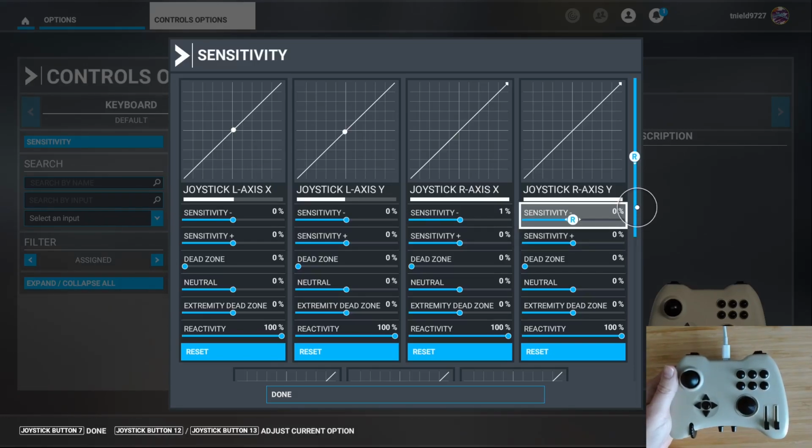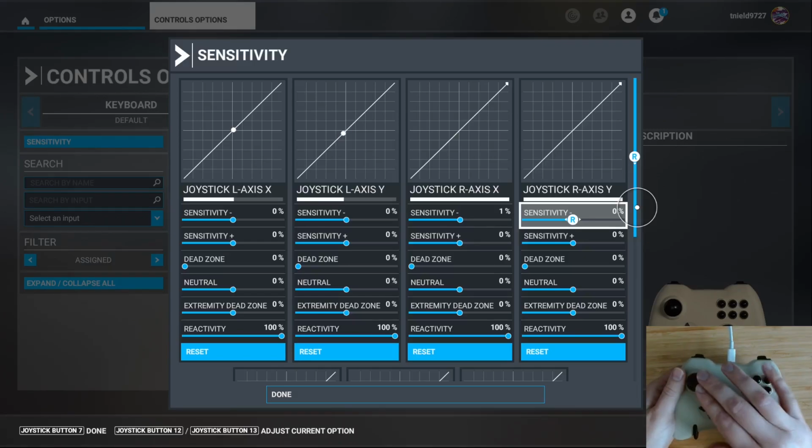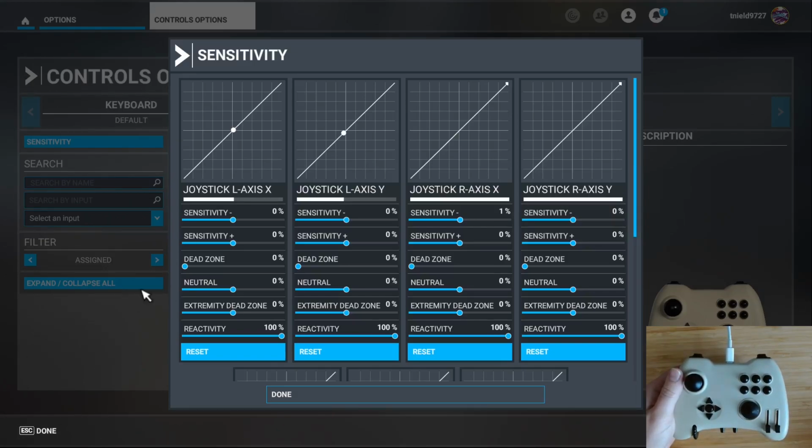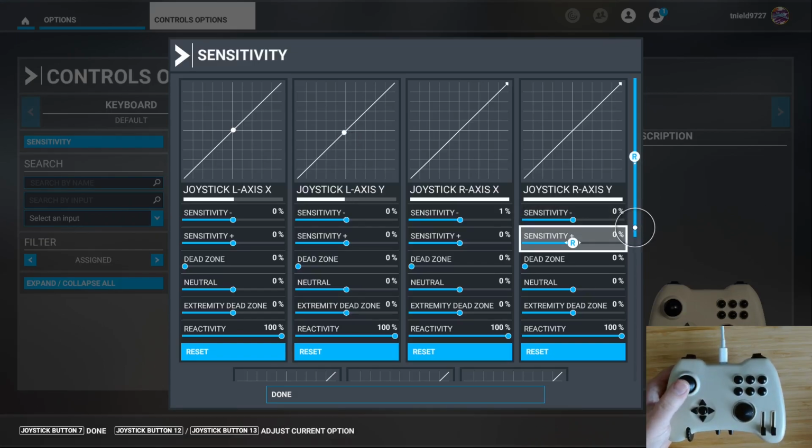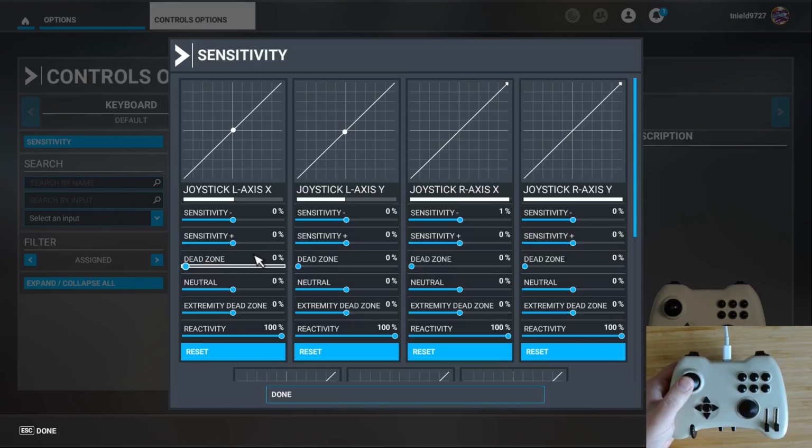Now I want to emphasize, we have very high quality thumbsticks put in the controller that have an extremely tight variance. But still, even then, you might consider putting a dead zone, a very small dead zone, to account for the fact that this dot doesn't always go back to 100% center, and that's fine. This is expected with mechanical controls. There's always going to be some degree of dead zone that we need to implement. Or you may not need to implement, you may be fine with it, but perhaps you want to correct that behavior if you're noticing for any reason it's affecting flight on certain types of aircraft.